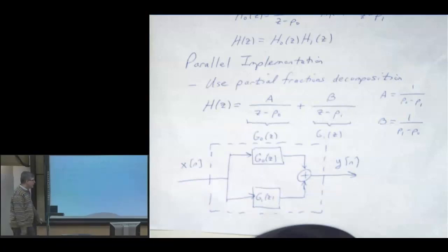So that doesn't really help us. But on a field programmable gate array, we can do these two in parallel, and that means I can run these twice as fast as if they were in cascaded form. Go ahead. So are you saying that also the reason why we keep it in factored form is so that we use less memory as well?